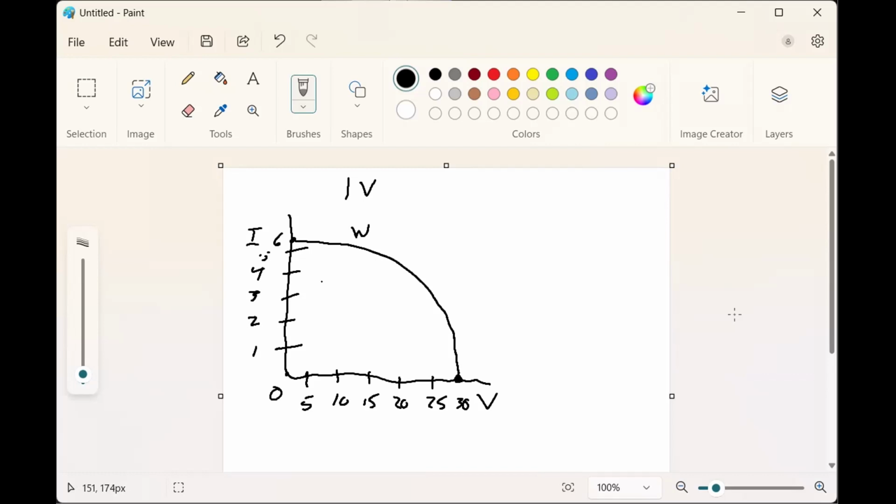And this is ISC, amps short circuit. It's the theoretical maximum amperage, but at ISC, nothing is moving. There is no power flow, so it's 0 watts. So that's a bad situation, basically a short circuit. And that is the maximum amperage, theoretically, but there is no power. So it's a bad situation. Now let's say we go up to 5 volts. Let's assume it's still at 6 amps.